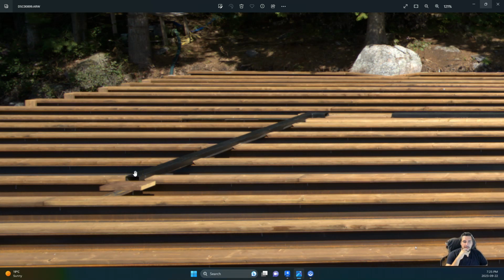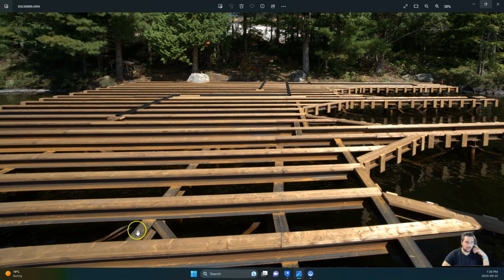And then the last part is, over top or underneath our walls, we actually put steel tubing. Definitely not something that we came up with, but it's been an industry standard for a number of years. What this has allowed dock builders and our clients to do is, as the dock boards rot, because it's usually the first thing that'll fail on a boathouse, they aren't going under the walls, and it gives some structure and some longevity to the building itself. So that's a general overview of what we're modeling.